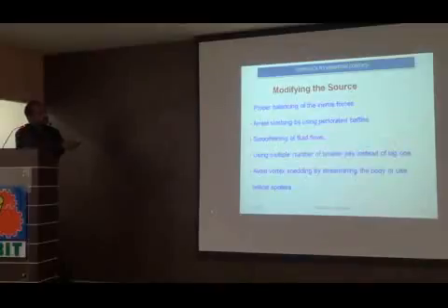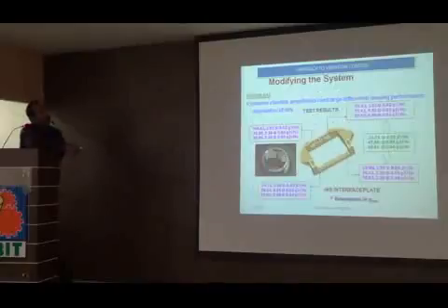As I said, I am mentioning different options available for reducing the vibrations. If you want to modify the source, you do proper balancing. If it is a fluid induced vibration, use smoothing of fluid flows, using multiple numbers of small nozzles instead of bigger ones. These are the different options available, like avoiding vortex shedding by streamlining the body or using helical spoilers to reduce the flow induced noise.